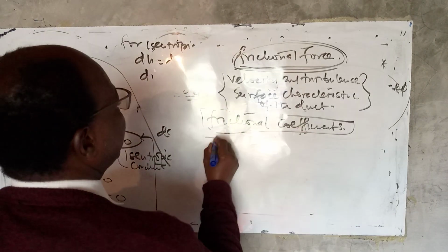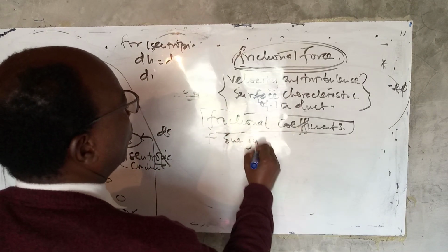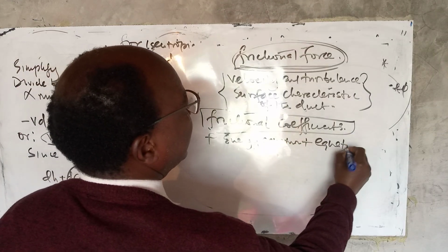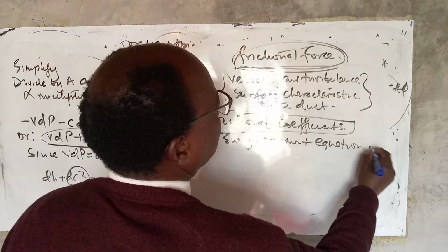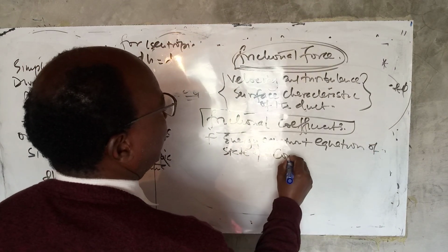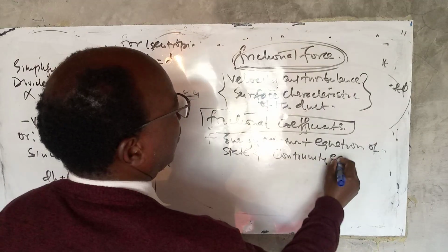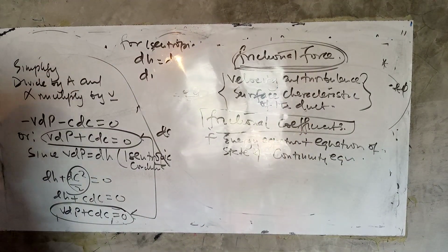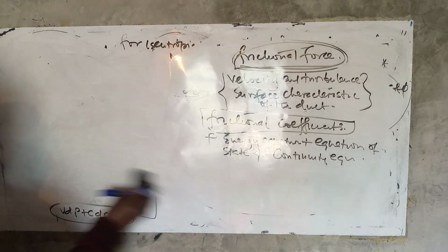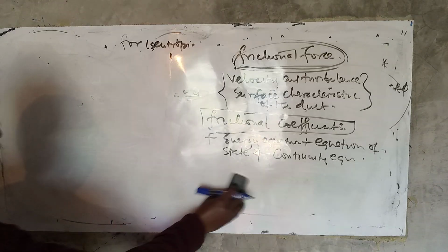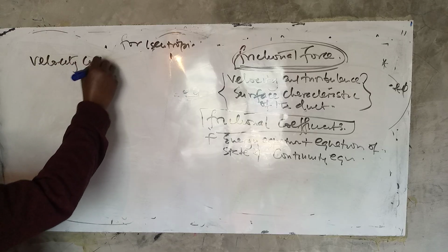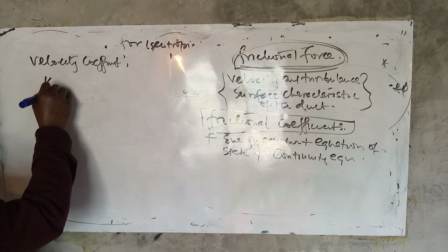So this complements, if you know the energy equation, you have an equation of state describing your fluid, and then you have your continuity equation, then you can compute these quantities. And some of the frictional coefficients which are used in these computations in the design of nozzles, for example, you have the velocity coefficient Kc.